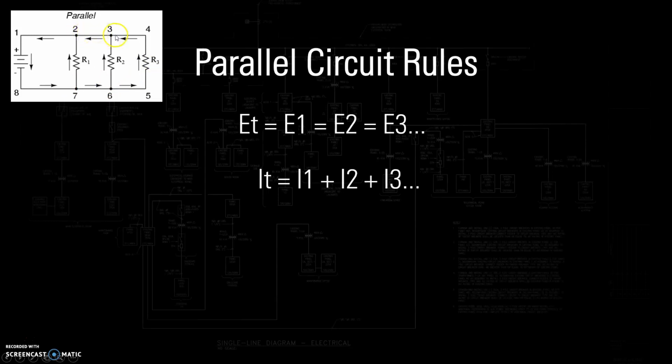Same with this portion of the circuit, we have 2 amps. We drop 1 as it goes through here, so we now only have 1 amp flowing through this section, until we join back up with this load and gain that amperage back. You can see that at any different point of a parallel circuit, the amperage is going to be different depending on how many loads are being powered on that portion of the circuit. The book has a nice diagram on this as well.